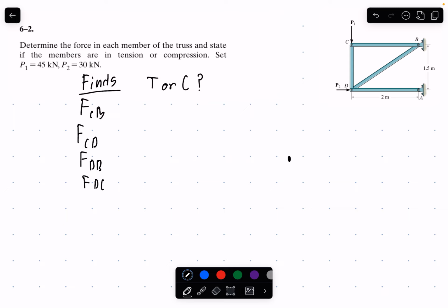So typically for these truss systems, you'll be analyzing the pins in these truss systems, which join these rods together. You can see them at points A, B, C, D. Typically these do not resist moments, so they'll only resist forces in the X and Y direction. Okay, and there are some reactions acting on this truss system, I should say, but for this problem, they're kind of unimportant because the problem isn't asking us to find these force members. So it'll be a free body diagram of point C.